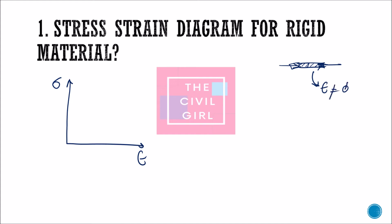That is, there is going to be no elongation at all. My strain is going to be 0. So no matter what stress I am applying, the stress can be from here to 0, say it is 100 here. No matter what stress I am applying, my strain is always going to be 0. So the curve for a rigid material will be something like this. It will not be a curve at all.